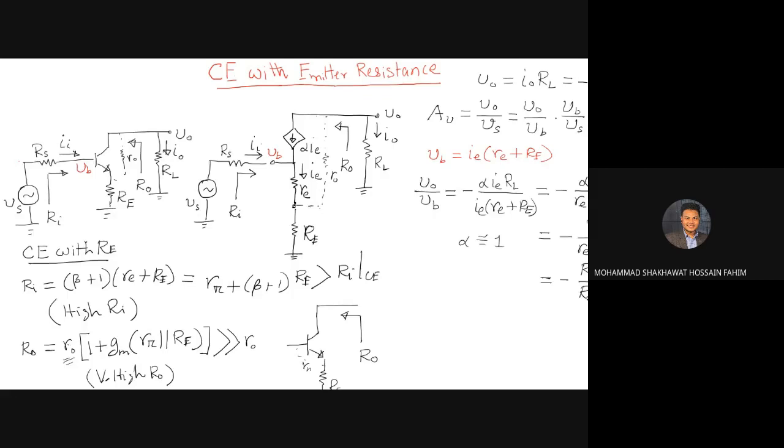Sir, what does this negative sign signify? The gain is negative. For positive voltage, you get negative output. For an AC signal, you get a 180 degree phase shift. Common emitter has negative gain, no? Yes, sir. What is the gain for common emitter?